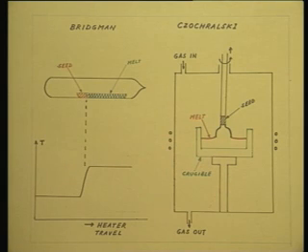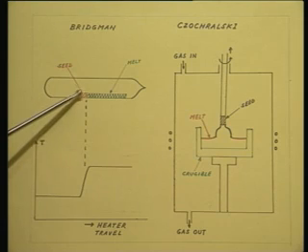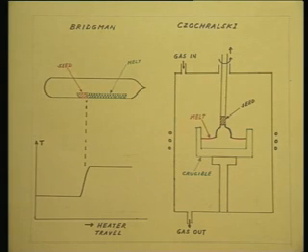In this boat, a seed crystal, a small single crystal is placed, and the rest is filled with the charge. What do I mean by charge? I mean the high purity silicon, which is polycrystalline or powdered, that is called the silicon charge.